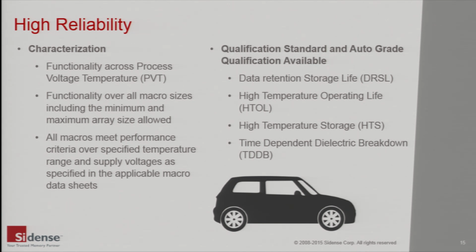Sidense also offers an automotive package with testing and compliance to AEC Q100 grade 0, and also some specific vendor testing like PPAP, which is Production Part Approval Process standards. These often include higher temperature testing at 150 degrees C and higher, and also additional services like DFMEA.